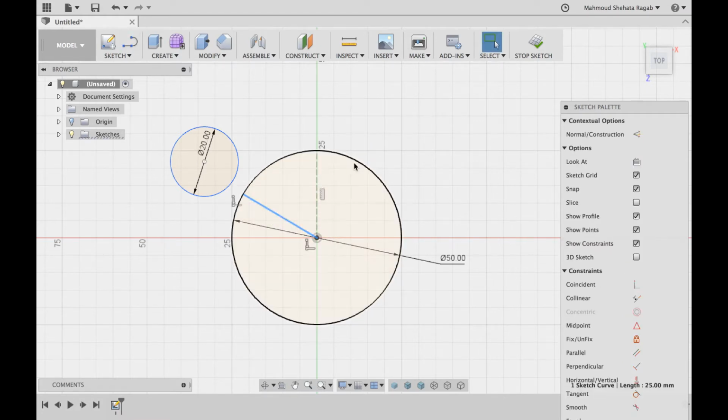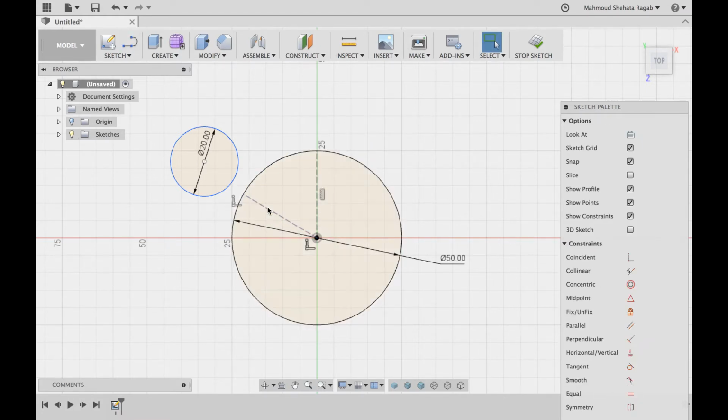Again, this line is also going to be construction. Now these two lines represent the center lines of two slots that are going to be next to each other. We just said that because we have 6 dwells, the angle between these two centers is going to be 60, exactly like I did here. It's going to be 60. Okay, that's good.